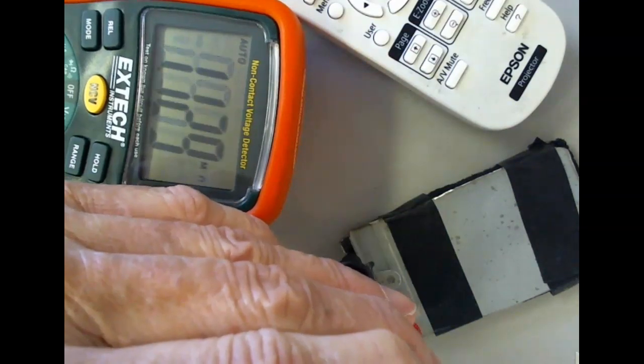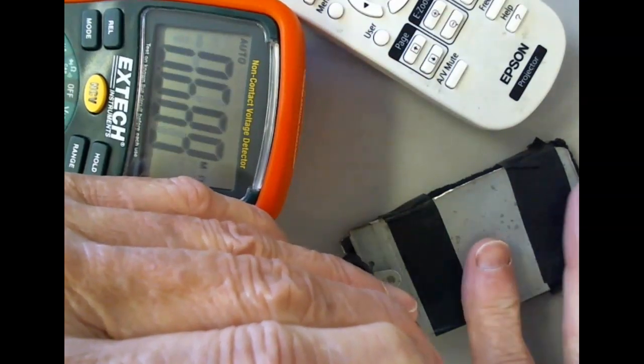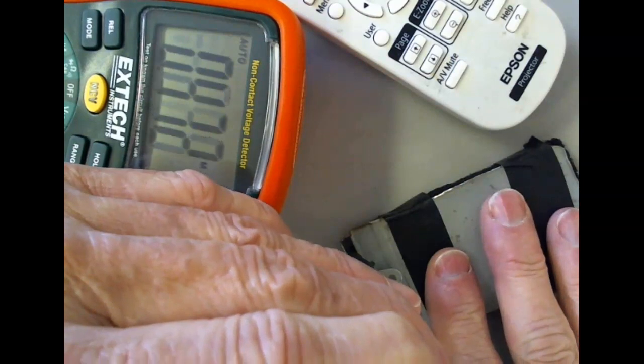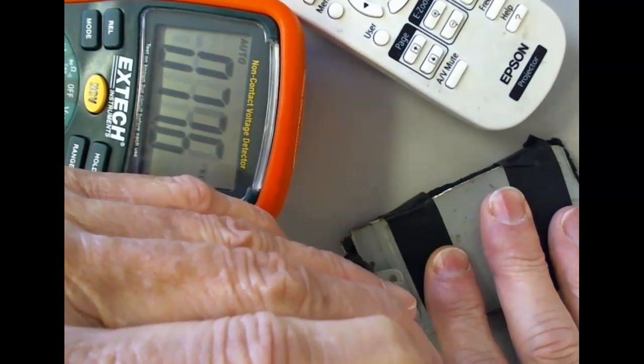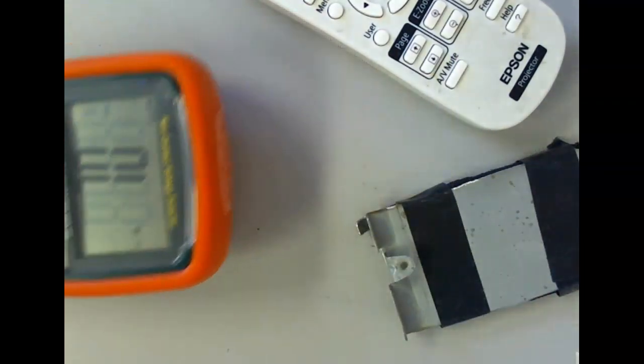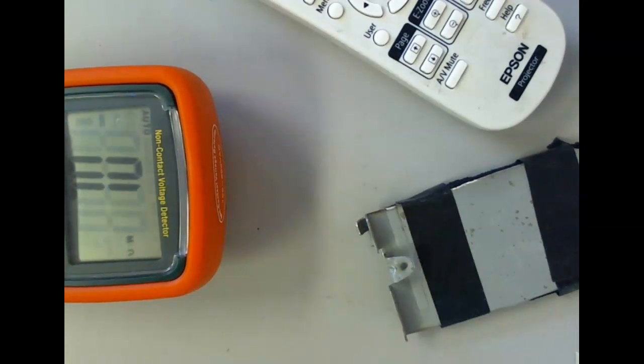So you see the resistance goes down. These are not very accurate, but like pads, like we said in robotics, they don't have to be accurate. All it's trying to do is sense a big change in resistance, and all of a sudden it will trip the robot if you walked into the work cell.